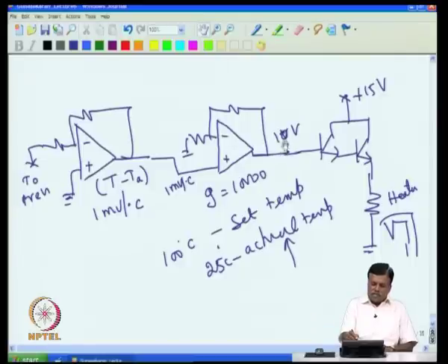then for example in this case our heater voltage cannot go more than 15, then once it comes to 1.5 millivolt, that is once the temperature reference difference is 1.5, this becomes 1.5 millivolt and this has come to 15. If the temperature difference is less than 1.5 degree, then the difference will be less than 1.5 millivolt and this also will come out of saturation, that is, also come below 15. That means this is operating in the linear region and this also will be operating in the linear region.